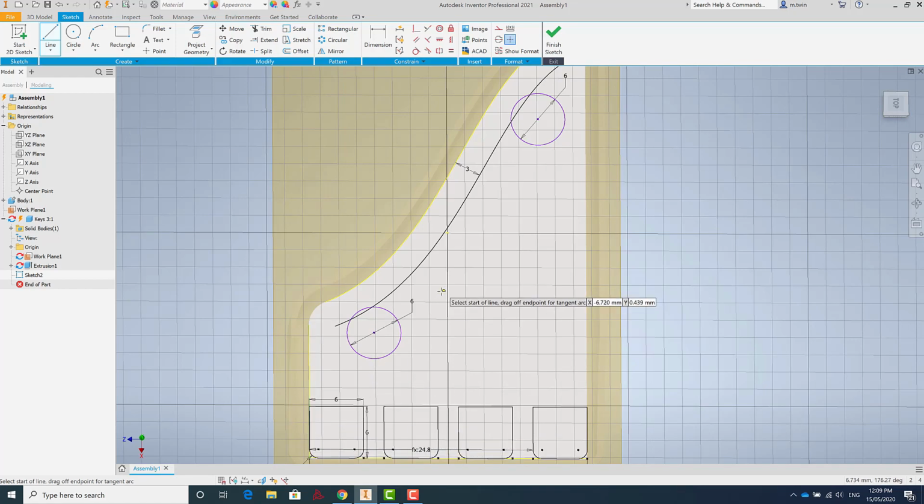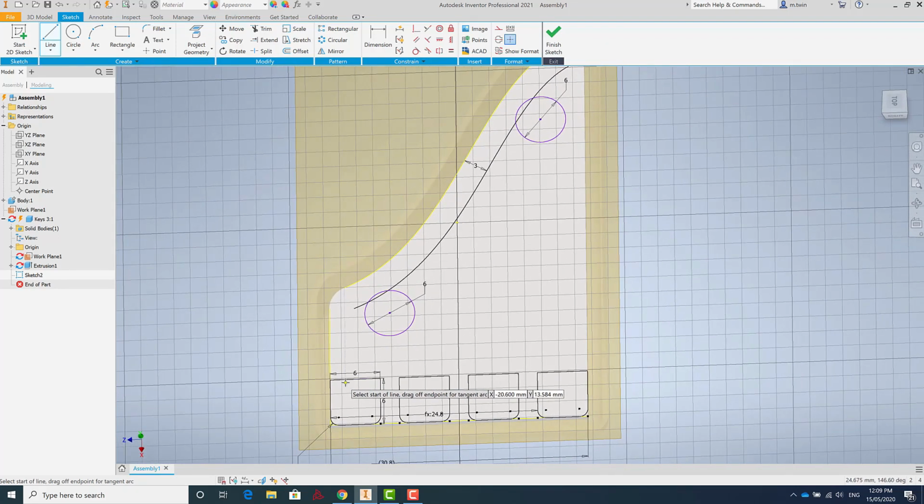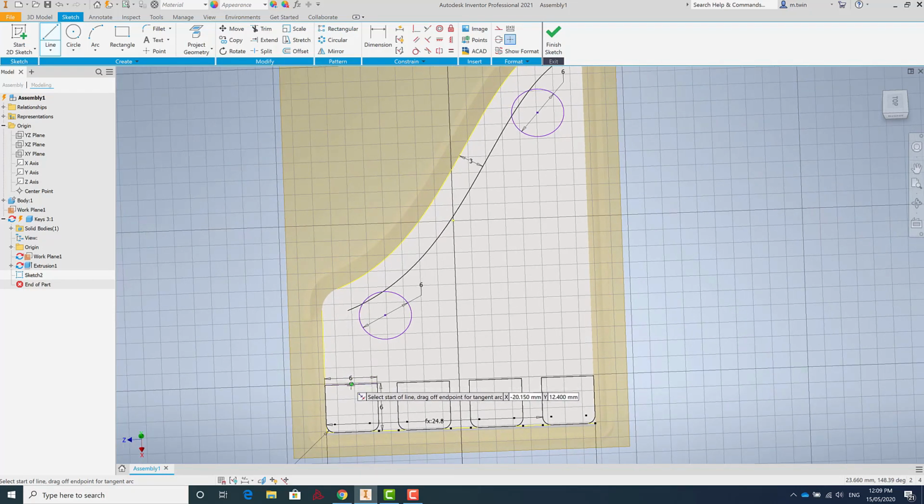Now we've got our rough position of our mounting holes, we can start positioning where our little arms are going to be. So we'll bring that one up to here. Again, starting in the middle, you notice that it started off with that green dot, and that green dot indicates that we're in the middle of that piece. The length here I've got set to, there we go. So in this case it's a fairly arbitrary number here, 9.319, but the important thing is it's 0 degrees. 0 degrees means that it's facing directly up and down.